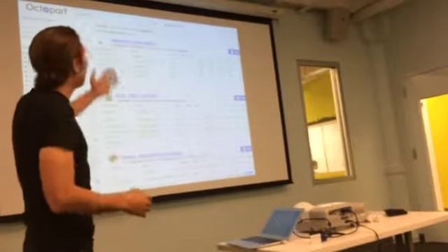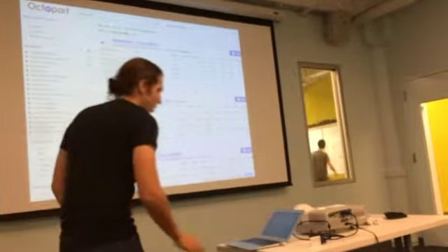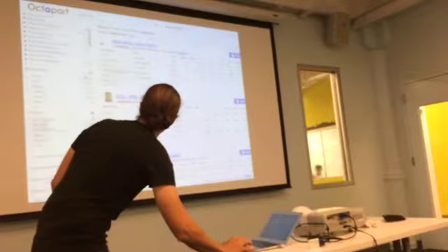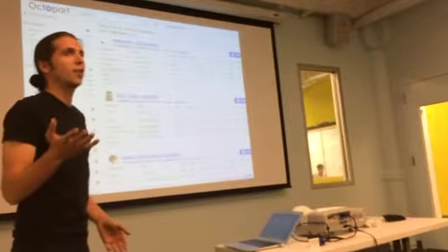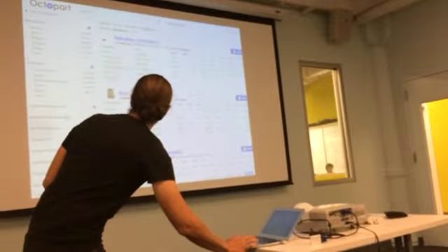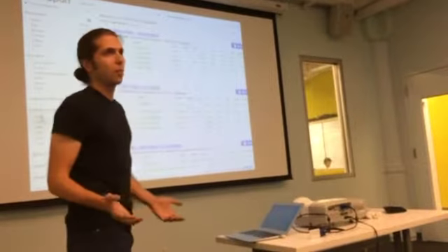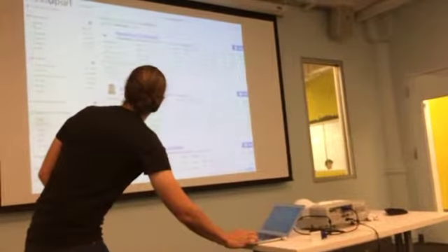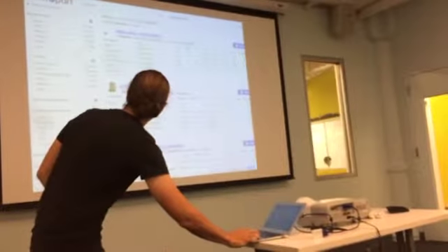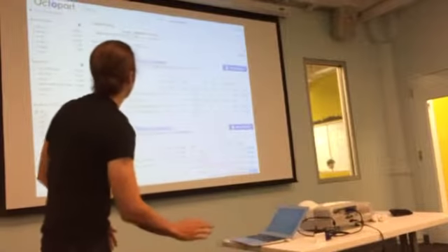And so we've got over 1 million capacitors in our database, right? Now we've got to narrow this down. So we had a request for X7R, and I know that that's a dielectric characteristic of a ceramic capacitor. So we'll click on the dielectric characteristic box, and then X7R is the most popular one. It's a little hard to see on the screen, but this is a little checkbox. So I click here, and now we're filtering on only X7R capacitors.